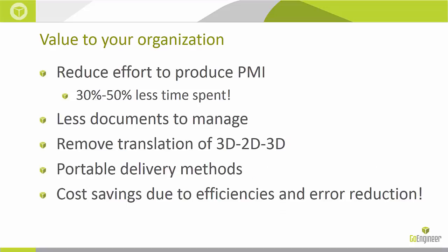So when we talk about MBD, we have to talk about the value to the organization. If there's no value to it, you're not going to use it. What we found is that with MBD, it reduces the effort to produce the PMI, right? So we're spending less time on the manufacturing information. There are less documents to manage because now I'm dealing with just a 3D CAD file instead of the 3D CAD file and all the documentation that goes along with it.